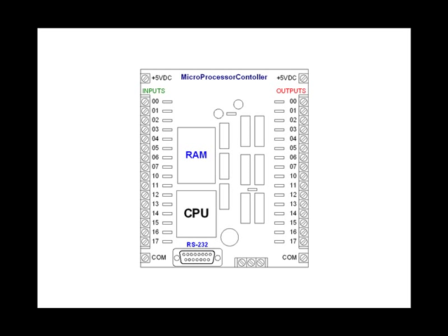The base 8 number system has 8 symbols, 0 through 7. There is not an 8 or a 9 in the base 8 system. Remember, this first position is units, the second is 8s, the next is 64s, then 512s, and so on. In this case, we have units and 8s. 10 means one 8. So when you see 1-0, if you look at the inputs, it goes 0, 1, 2, 3, 4, 5, 6, 7. Then it looks like 10 through 17. That's not ten, because this is a base 8 number system.